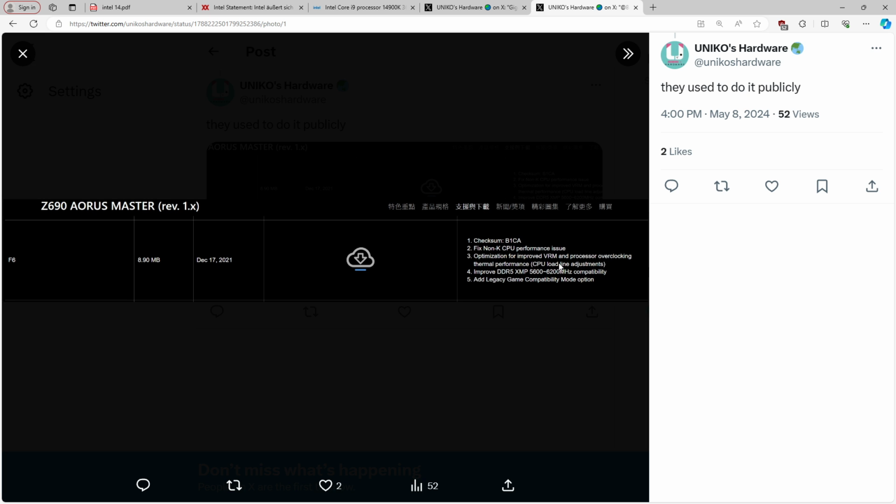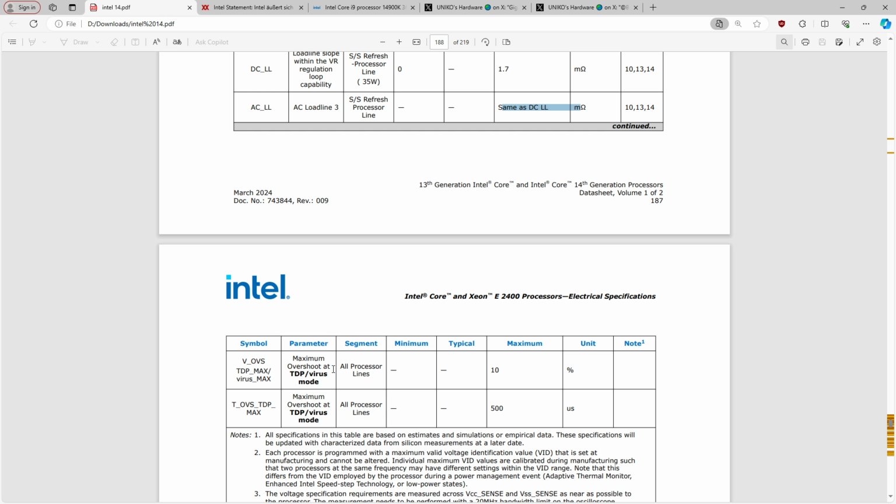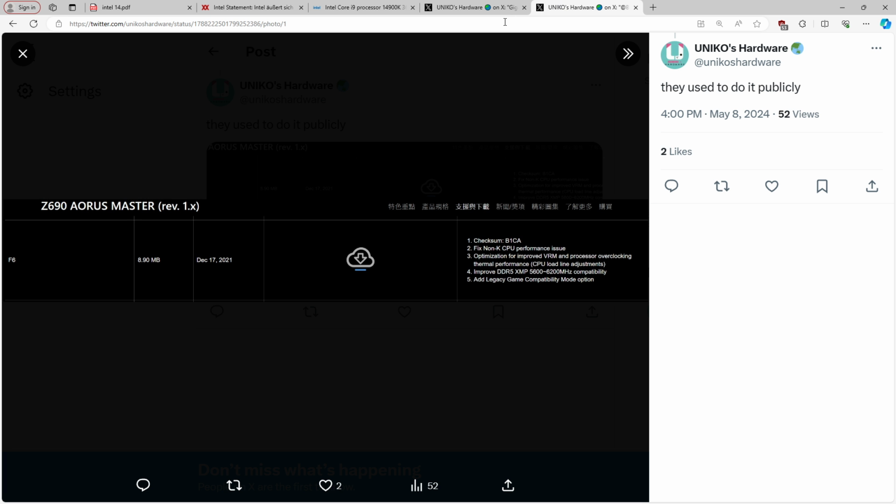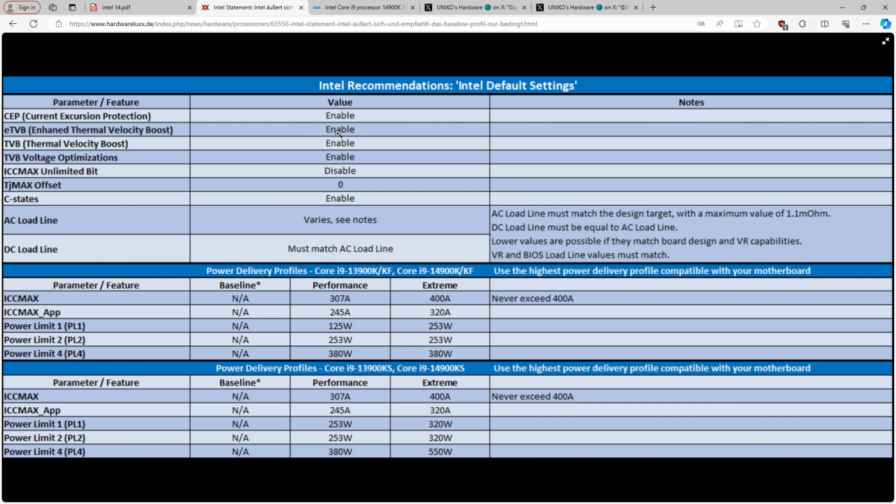And it's not because your CPU degraded, it's because the motherboard vendor has progressively undervolted your CPU more and more with each BIOS update. Or the latest BIOS update just runs, you get the idea. It's actually just running less voltage, which might be why you're unstable instead of the CPU actually degrading. But it is still possible that some CPUs did degrade, and I imagine the recommendations from Intel over here won't fix anything if your CPU is degraded.